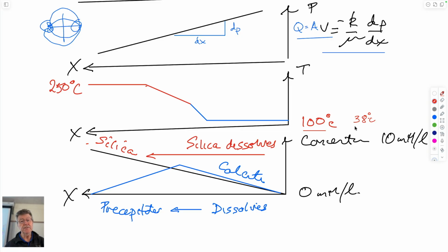I think also this is the boiling point for IPA. So if you run your geothermal fluids after you flash it to steam and condense it at 100 degrees centigrade, you can put it through an organic Rankine cycle plant, which boils isopropyl alcohol. Its boiling point is 38 degrees centigrade, and it changes phase from a liquid at any temperature above 38 degrees centigrade.